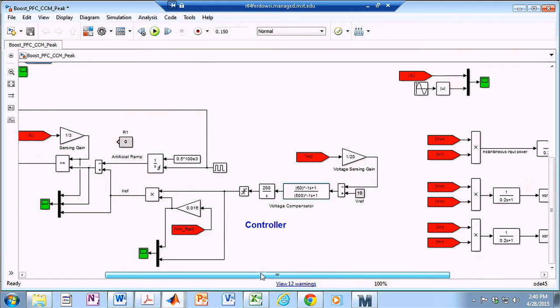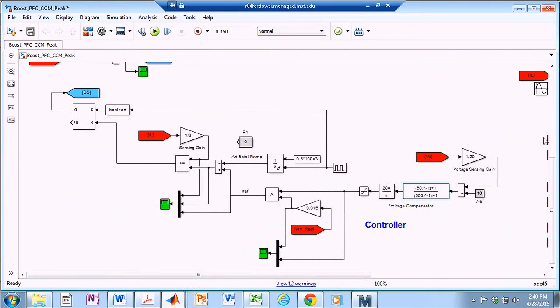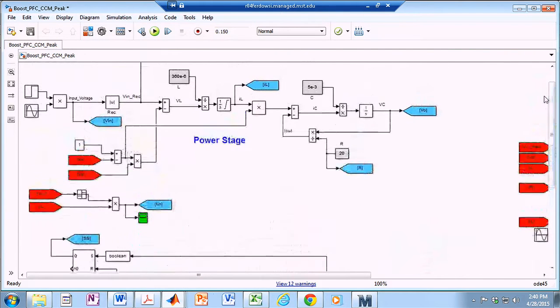All right. Another thing that I'm going to talk about is, yes. When we are increasing the poles and the zeros frequency, then the bandwidth should increase, right? The bandwidth should, okay, just a little bit. And the response should be a bit faster than... Well, ideally, yes, but there are so many other crazy things happening here, and we didn't drastically change it. We only moved them 10 times to the right.